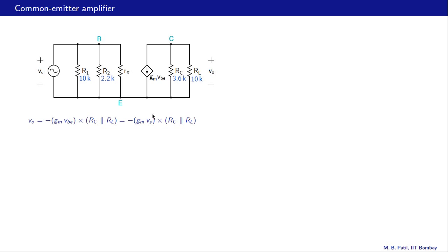Here is the AC circuit again, and we have added the component values. What we want to do first is to obtain the gain for this amplifier, that is Vo divided by Vs. And let's remember that all of these quantities, Vs, Vo, VB, etc., are signal quantities. All right, so let's look at Vo.